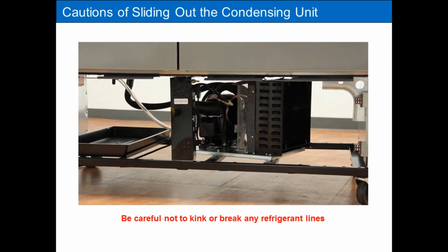Now I did come to realize that it wasn't how I pushed it in that caused the problem. The suction line had a rub-out already started, and I just aggravated the situation by pushing it back in. Luck of the draw is that I pushed it back in and it gave free. In any case, be cautious anytime you're pushing the condensing unit back in or taking it out of its cavity. You may create other problems that you were not there originally for.